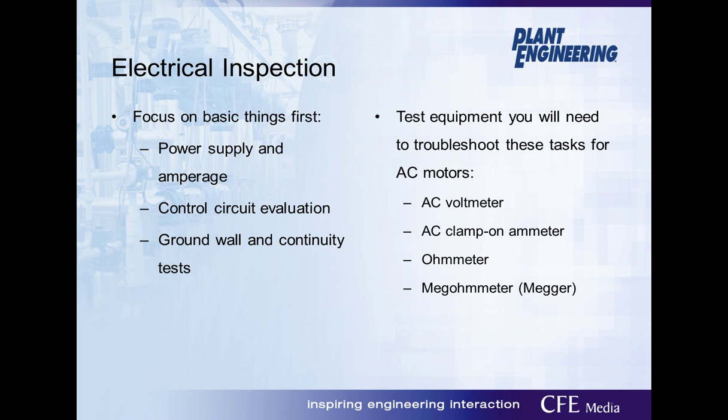First, we should know that it is best for these tests to be performed by someone who has been trained in electrical testing. By using a voltmeter, we would first check for applied line voltage at the power supply of the motor at each line to ground to eliminate any potential blown fuses. And then we could proceed to test each phase line to line. The applied voltage could be direct wired from a simple on-off switch, or it could be coming from somewhere a little more complex, such as a VFD or soft starter. When performing these tests from a control circuit such as a VFD, we'll want to make sure that the power is available at the incoming and outgoing side of the unit when in run mode.